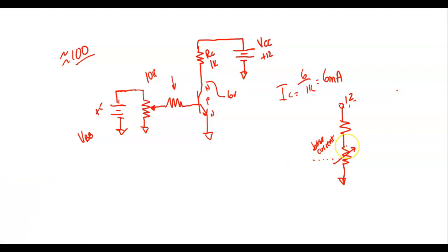But what's controlling that? So a rheostat, who controls the resistance of a real rheostat? You do. You have to turn a knob. What's controlling the resistance of this rheostat? Base current. But we can change it all over the place, right? So we've got 3 options. We can operate it like this, or I can operate it like this. We call this saturation.